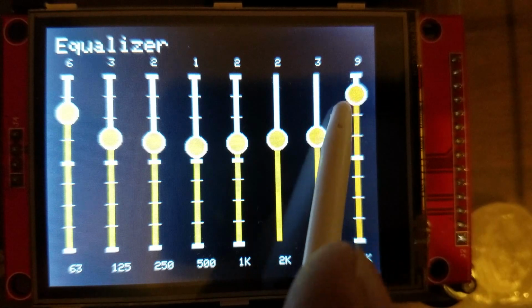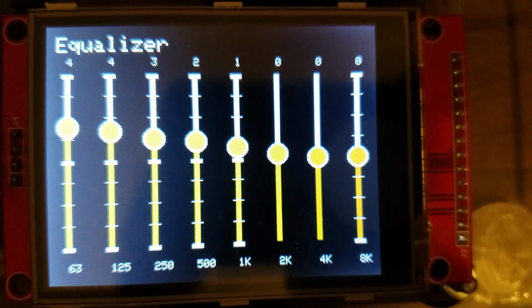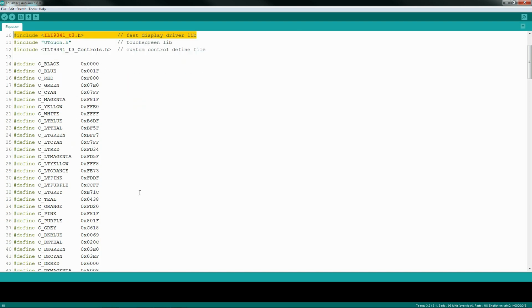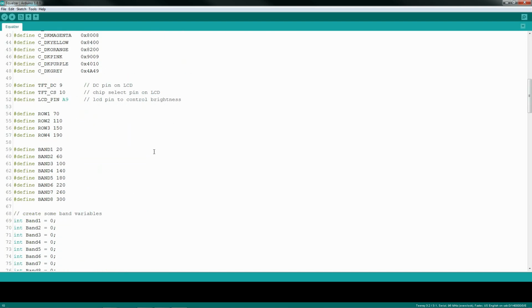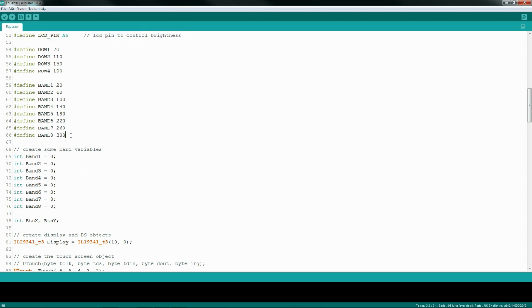Once you look at the example code, I think you'll see how easy my sliders are to implement. As with any library, include it first. Note, this library was written to work with the Teensy's ILI9341_t3 library, but can work with just about any library that leverages the Adafruit GFX library. See the description on the GitHub site for details.